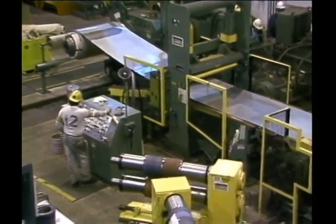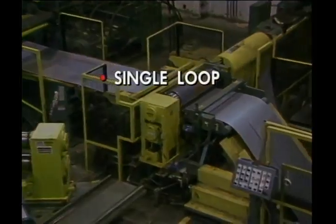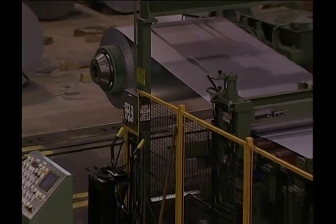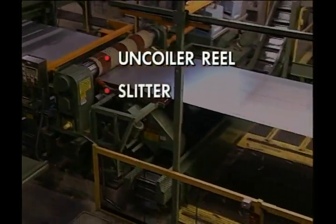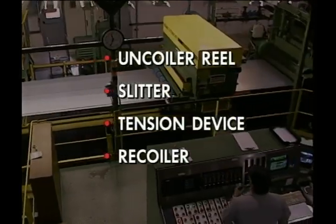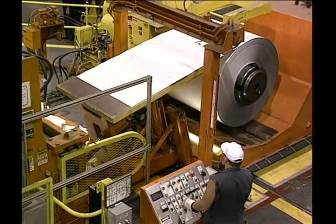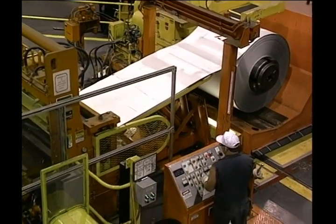Slitting is accomplished using a slitting line, of which there are 3 basic types: the single loop, the double loop, and the pull-through. These slitting lines consist of an uncoiler or payoff reel, a slitter, a tension device, and a recoiler. The uncoiler reel holds the master coil on its inside diameter using a mandrel. The coil stock is then fed to the slitter by rotating the mandrel.